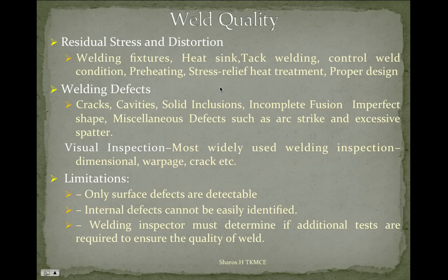Stress relief heat treatment is another process which is done to remove the residual stresses which are embedded into the joint after the welding process. Then the visual inspection, we can inspect the welding processes by visual inspection, which is the most common process. Then we can identify the cracks on the surfaces or warpage of the parent pieces or dimensional inaccuracy easily by visual inspection.